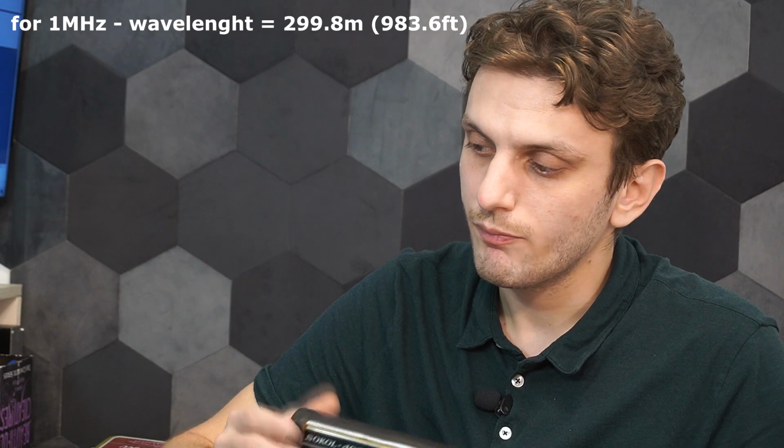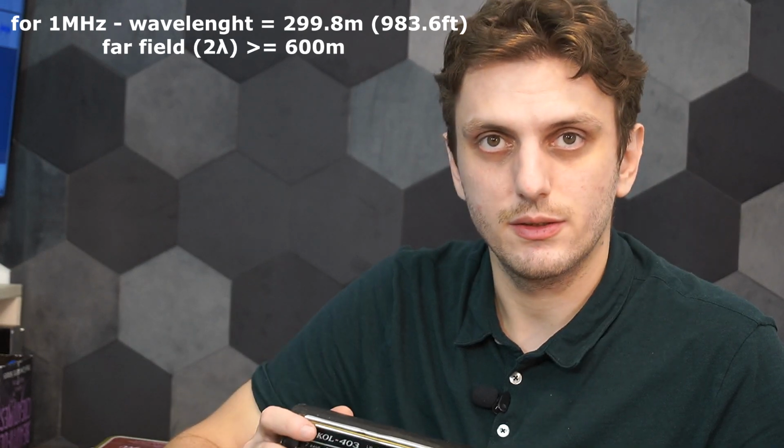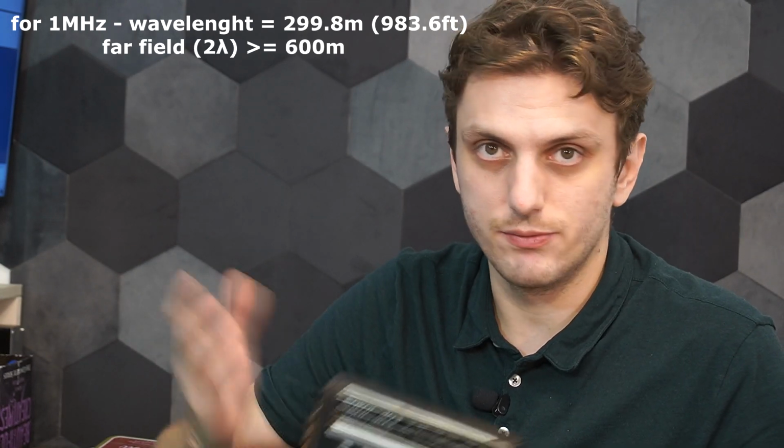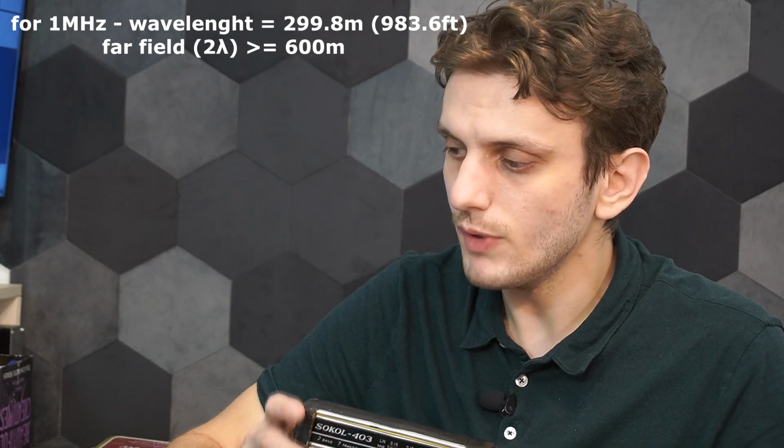But considering that we are working at very small frequencies, 1 megahertz is a frequency at which the wavelength is very, very long, radiating electromagnetic radiation on a short distance is virtually impossible. So the only other way we can take the signal from our circuit to the radio would be in the form of either electric fields or magnetic fields.